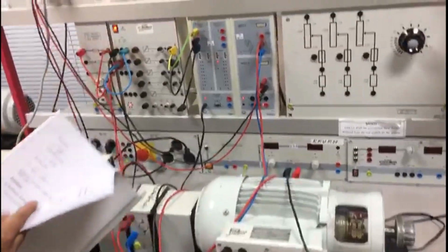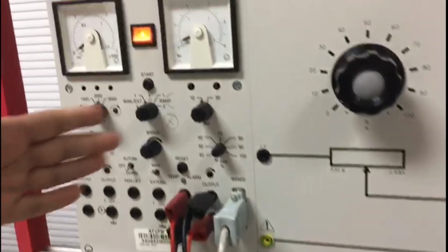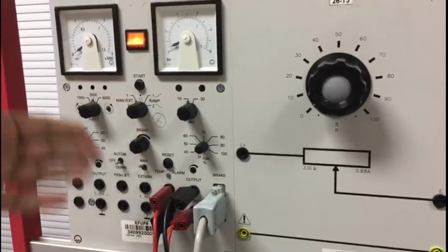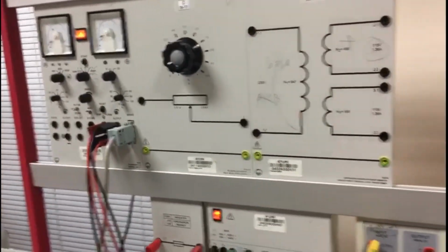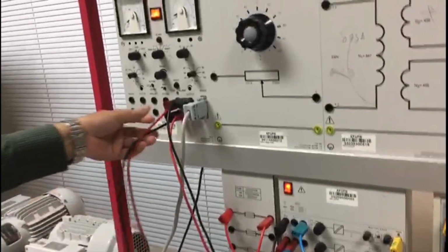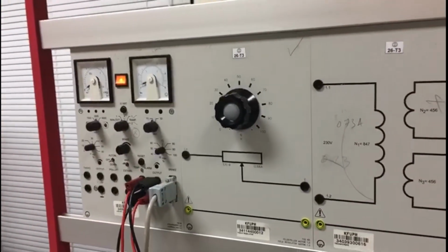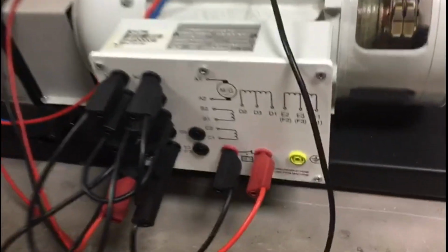Now we have made the connection for the DC shunt motor as per the circuit diagram given in the manual, figure 1. And you can see we have the control unit. This was already explained, and we have made all the settings about the torque and M maximum and the mode of measurement as per the manual. Now temperature alarm also has been connected. If the temperature exceeds, then it will trip and an LED light will turn on, and then you have to reset that after letting it cool for some time.